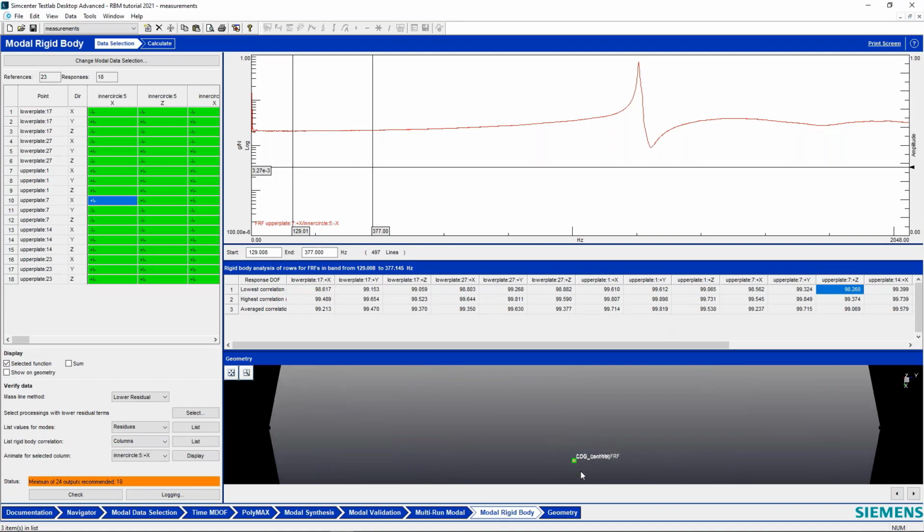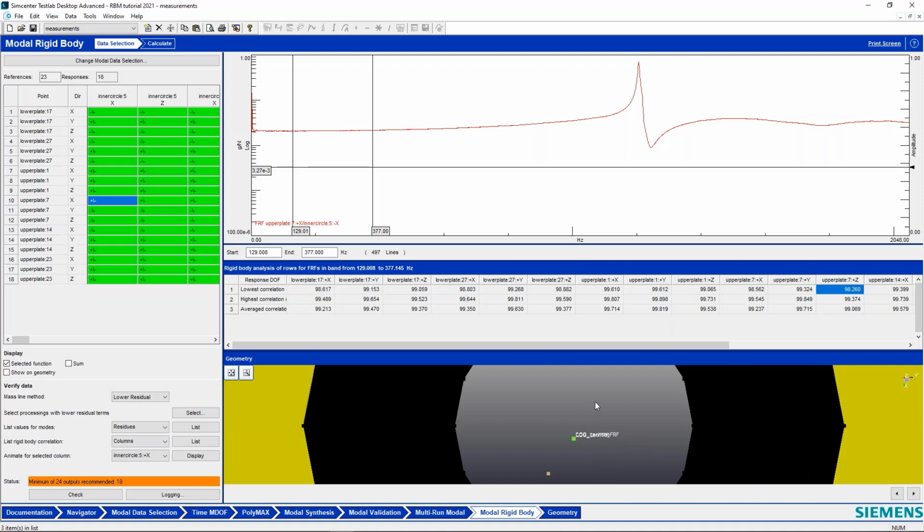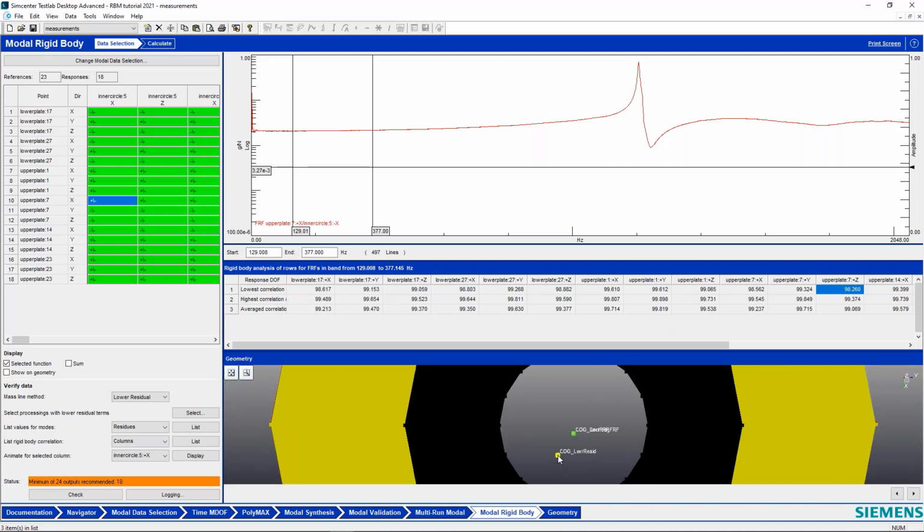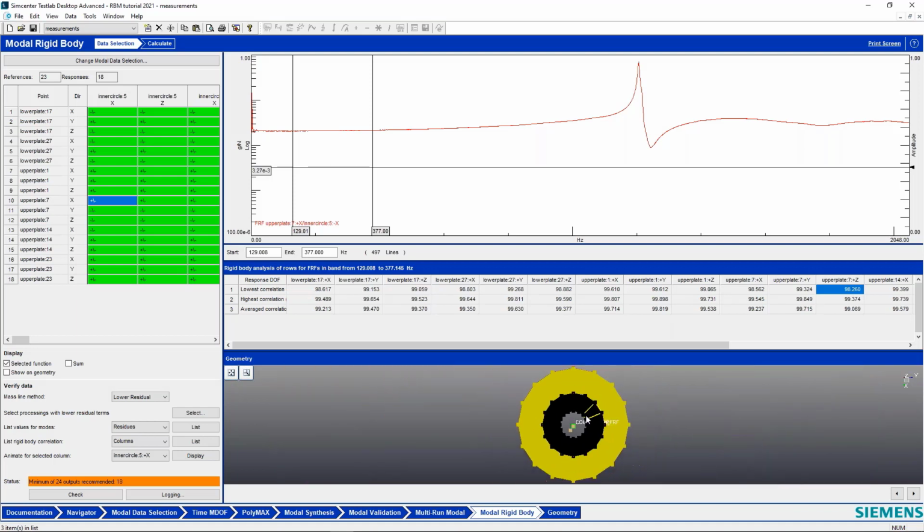there's the 2 degrees of freedom, one with the corrected FRF method and one with the unchanged FRF method, and they got really similar results. And the one over here is the outlier that used a lower residual. I didn't get good results with that technique with this particular data set.